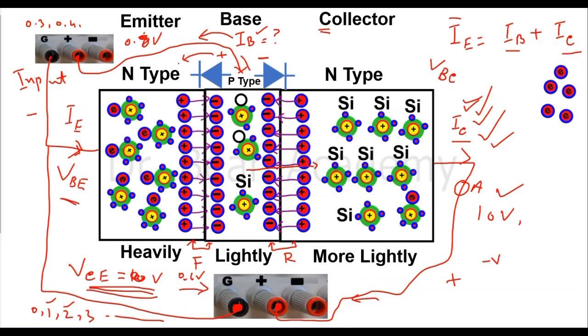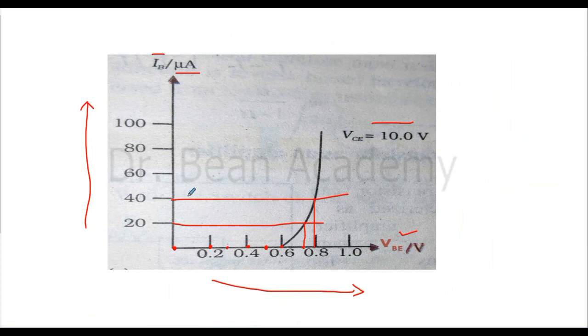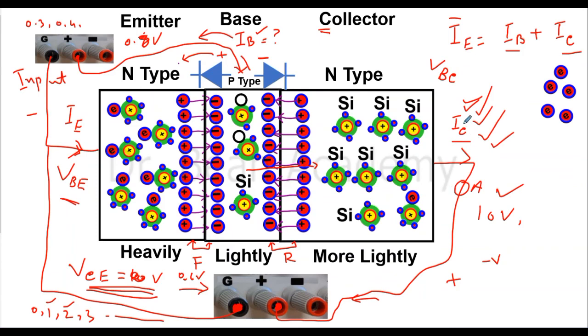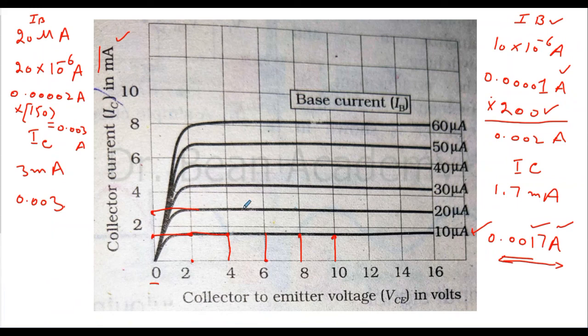After setting that voltage, you will get the 40 microampere current, then just leave it in this state, and now see the current at the collector, and then also change this VCE across emitter and collector and see what happens. So you can see that for a small base current you get a huge amplification of the current at the collector terminal. So you are using this transistor as an amplifier, and this amplification is really good.